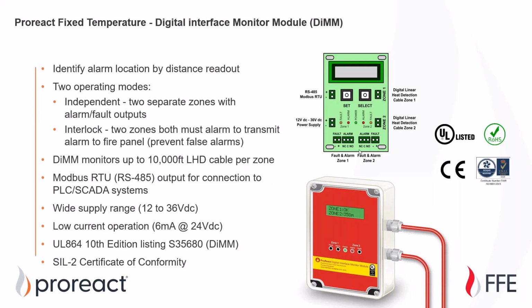There are also your alarm relays, relay terminals here, which can be monitored. So this is UL listed. It only draws about 6 milliamps at standby at 24 volts. And it has a SIL 2 certificate of conformity.